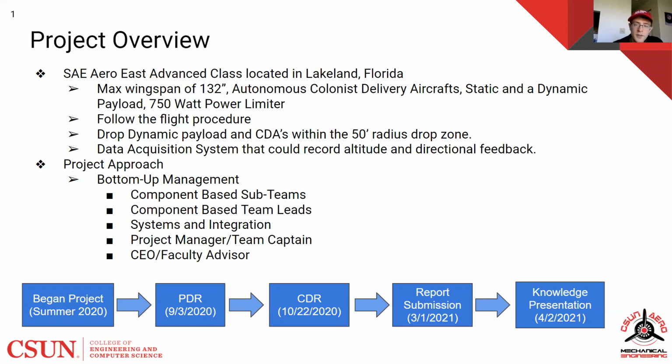Okay. So was there a lot of different iterations of the design that you tried out, or was it just a couple? There were different iterations. Initially we were testing about 4 different airfoils, trying to find the right one for our team. Once we learned early on that we were going to be manufacturing ourselves, as we were trying to find an outsource and couldn't find one, we opted to include manufacturability as one of the main considerations for the design. We knew we would have trouble later if we had, say, an airfoil with a really thin trailing edge to manufacture ourselves.